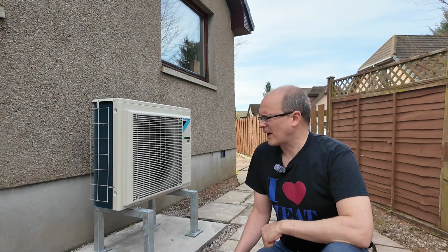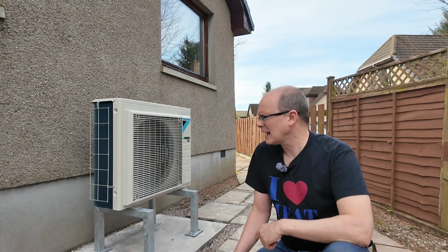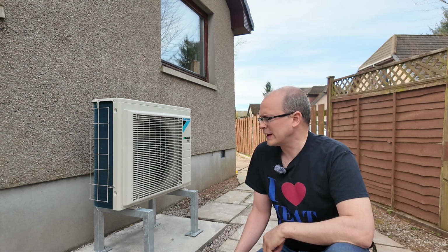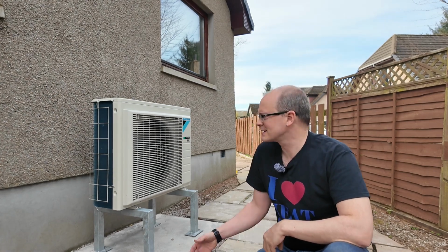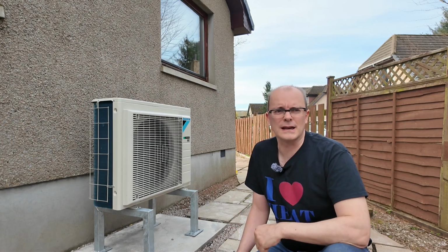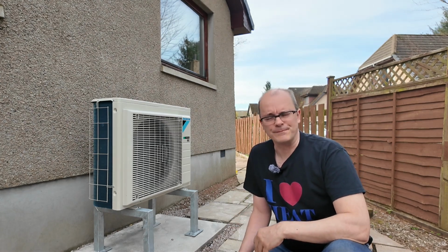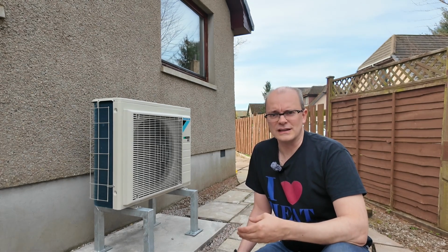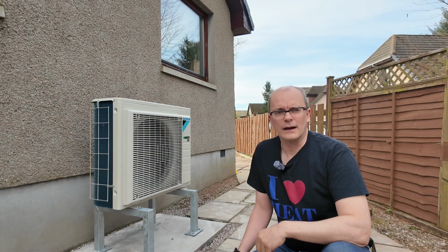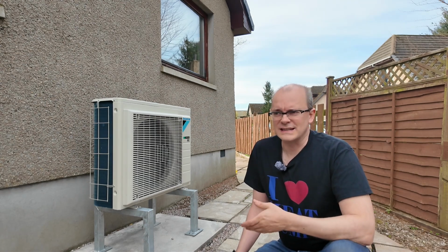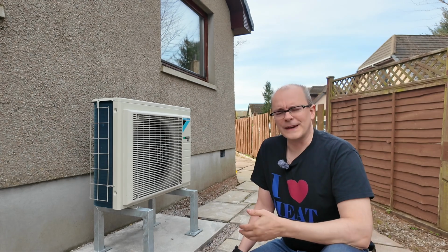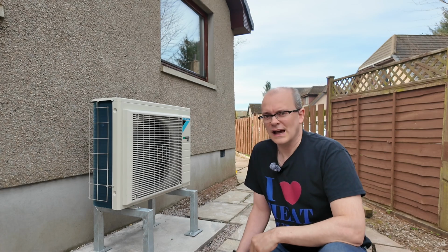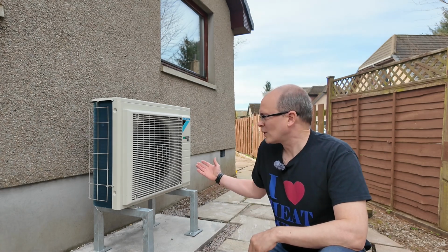Well, that's it as far as all the analysis for my heat pump is concerned. I'm going to show this to my installer and hopefully we can get a fix in place so that this thing can run at better efficiencies for milder temperatures. I've got a feeling it could be one of two things. It could either be a constriction in the return capillary line coming from the condenser. That is a hardware issue, of course, but the other thing is that it could just simply be a genuine software issue, in which case a firmware upgrade might indeed solve this issue.